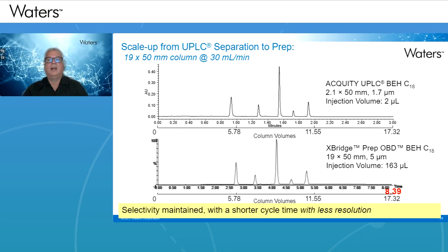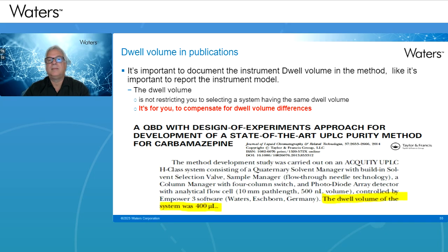Slide 54. Okay, so I will not repeat everything. I'm sorry for this interruption. We were going to use a column, but we have decided to go with a shorter one with increased flow rate. So the calculator is capable of giving you the appropriate values to still keep the same kind of separation, because we have not changed the mobile phase and the particle type, but we have a faster run, so we have lost in resolution, but that's okay. That's exactly what we wanted. We wanted to get more throughput in this case.